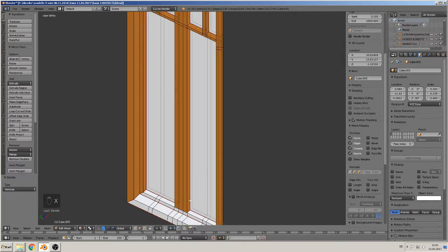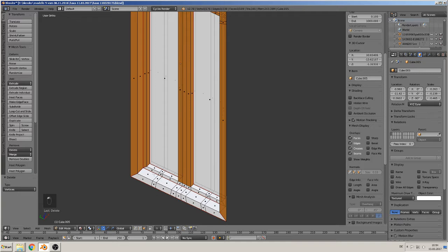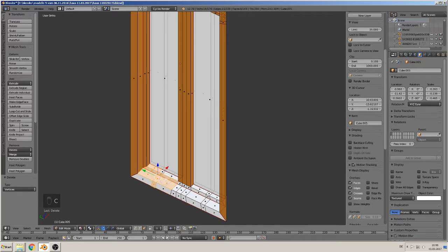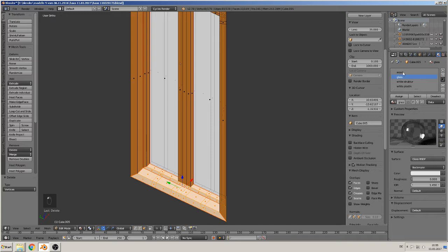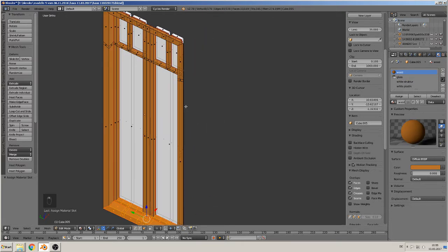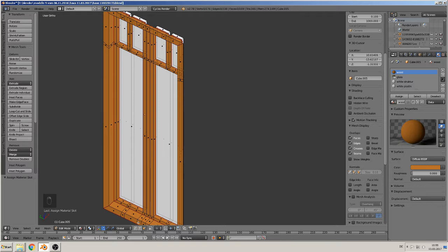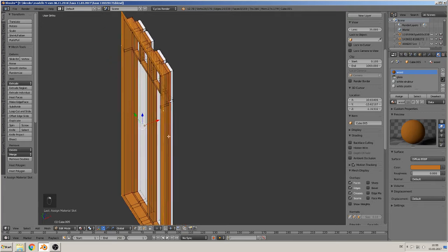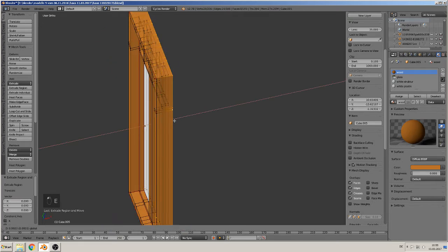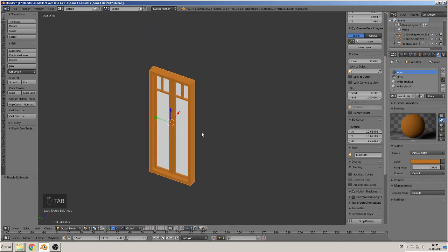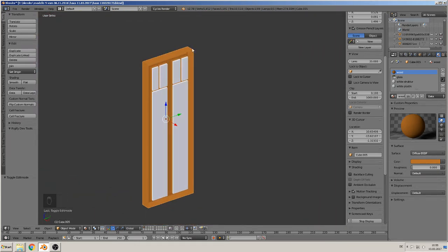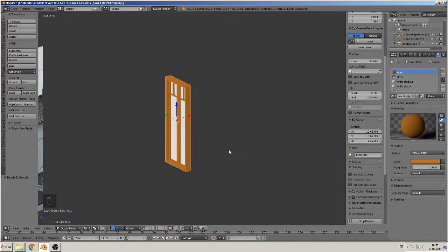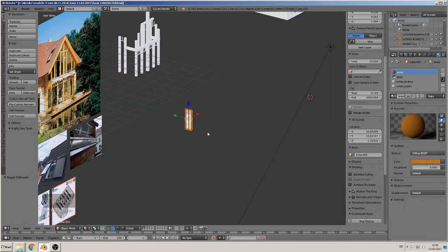So we can make here all with wood. That means we can select that and give them a wood material. Good. Here, wood, assign. We mark the outer line, complete, and extrude that to the back. Then we have closed that. Good. You can close it correctly there if you want, but nobody sees it later when it is inputted.